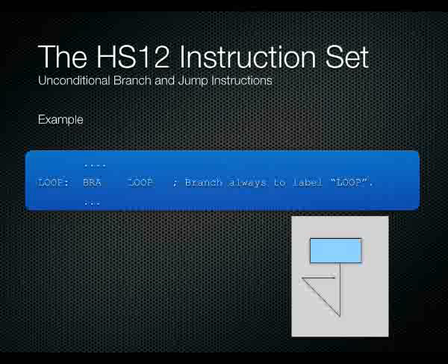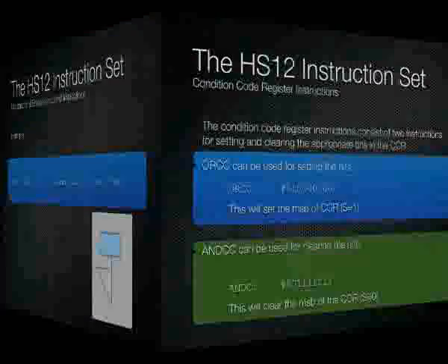So the last line of our program, we get it to spin on the spot like this, because if we don't, it will go and run whatever random data is in our memory space after the program we've uploaded, which will give us some undesired results. So we always try to stop our code, or have it in an infinite loop that never exits. If you don't have an infinite loop, you put one on the end using this sort of structure, where you get it to branch back onto itself.